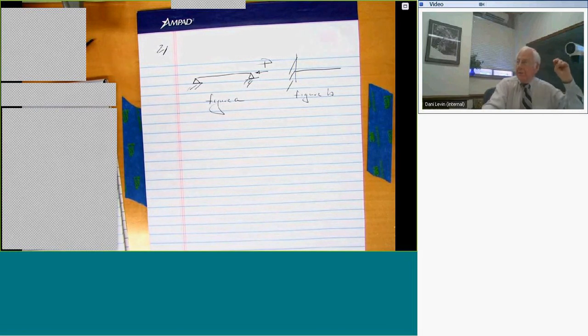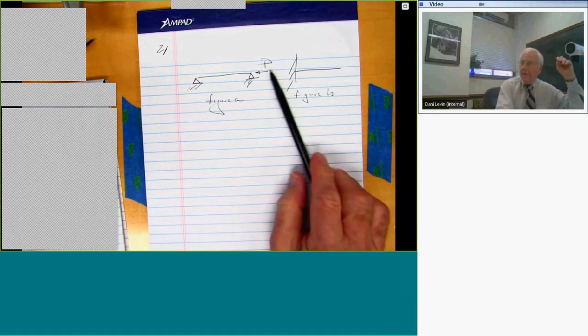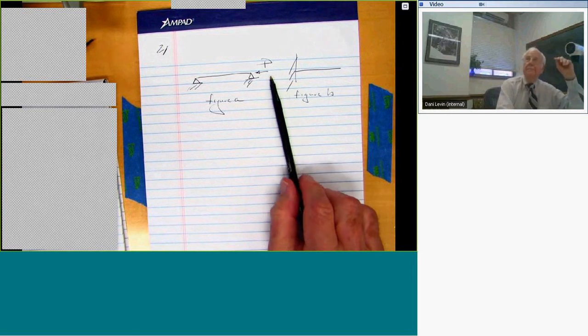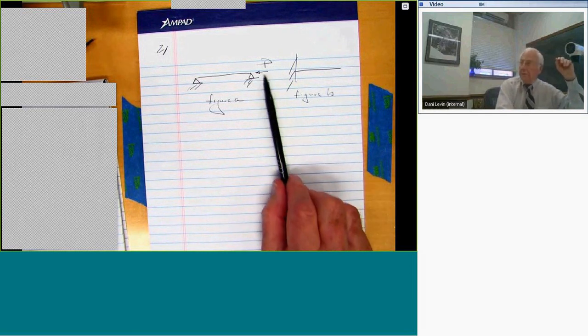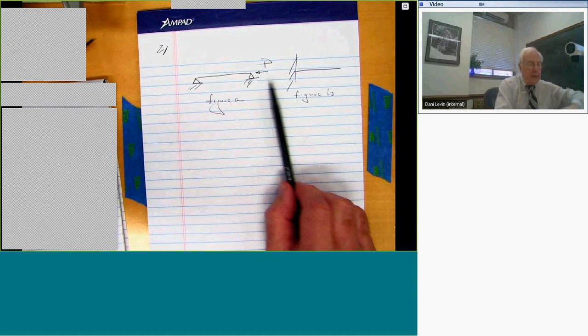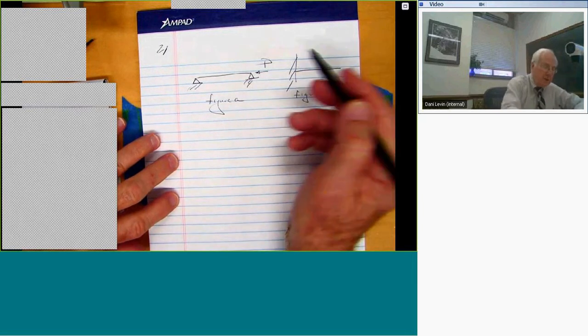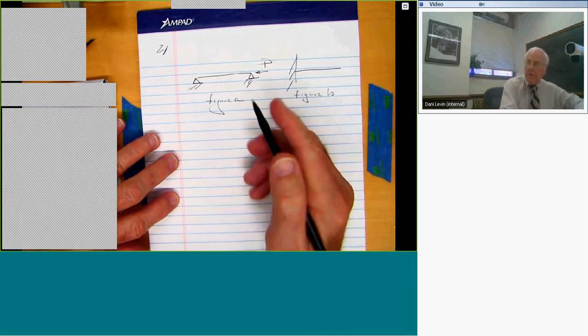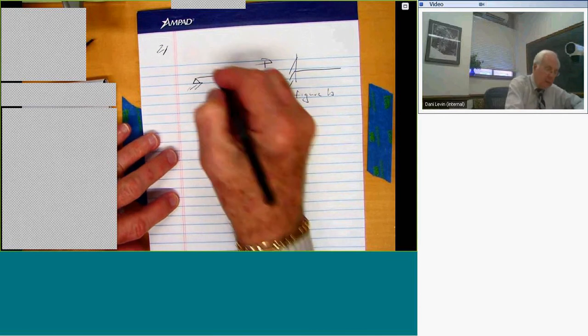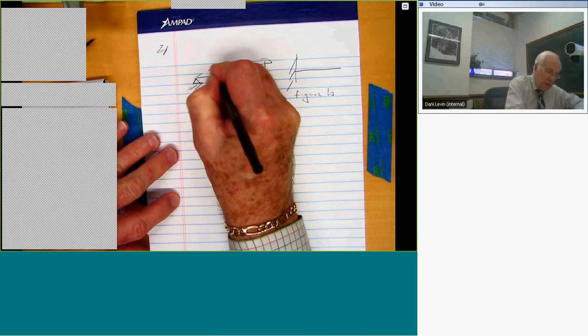Or if you prefer, divergence is the aeroelastic equivalent of buckling, and the aerodynamic forces are playing, very crudely speaking, the equivalent of this compressive load. Anyway, if you compress this and you hit the critical value of the compressive load, it will buckle.